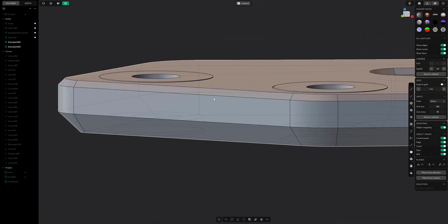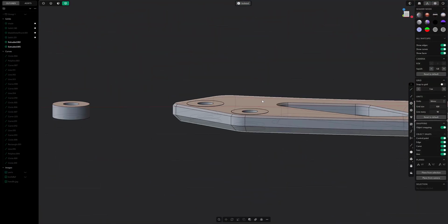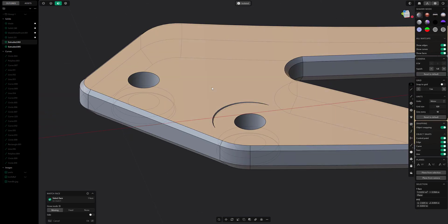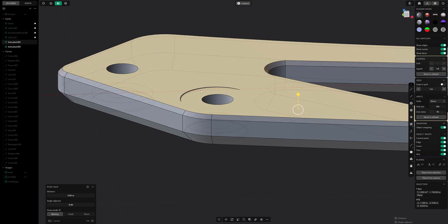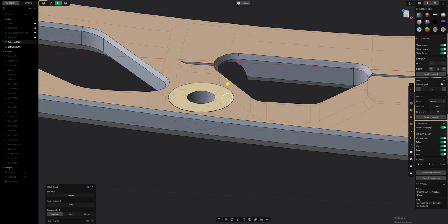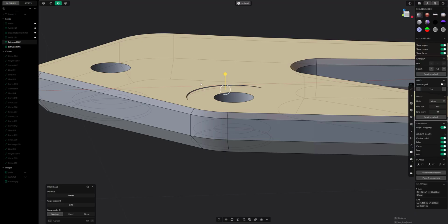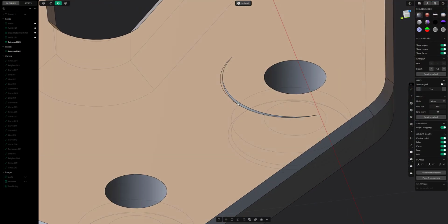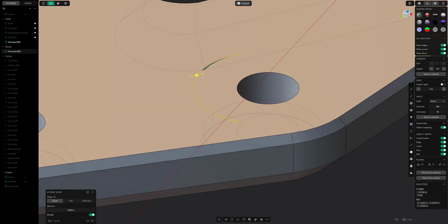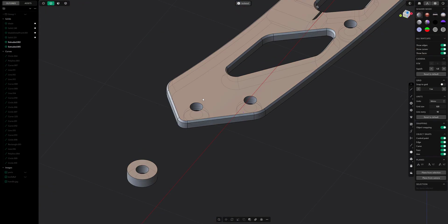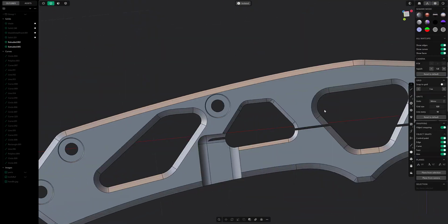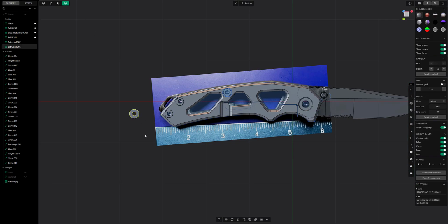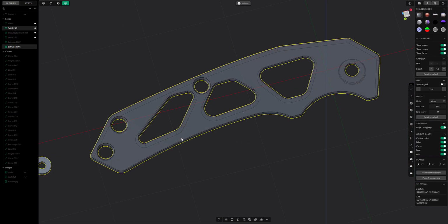These weren't perfect, so here I'm going to go ahead and select the face and just try to match face. That kind of worked, not really. So this one here I think does, but this last one I'm not sure. At first I thought that the area was not planar, which wouldn't make sense. So I just shift delete, and then we go and we patch, then hit down or whatever you have assigned to delete redundant topology. And then it's all clean.